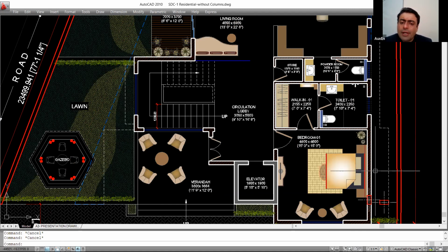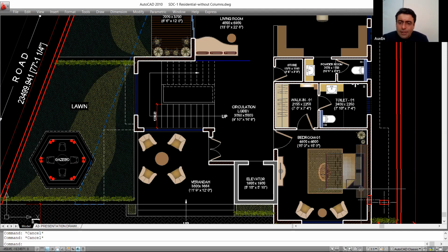Virat is saying load bearing. No, our brick walls are not load bearing in this construction. The construction that we are doing is a beam column frame construction, isn't it? So walls are not structural elements, neither the external walls nor the internal walls. None of them is a structural element. Mr. Shayaz is saying security purpose.